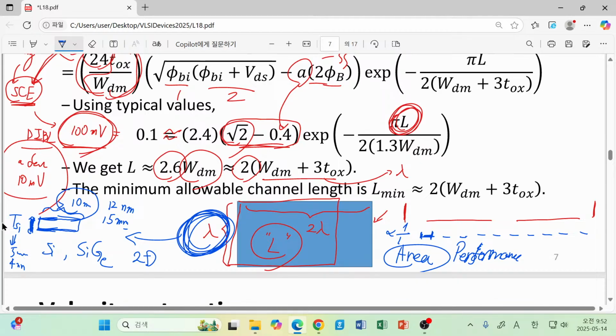We are quite at the extreme of our allowed scaling rule. We are already making full use of this scaling property. So the next thing is, well, 15 nanometer, 12 nanometer. It's good. By introducing this kind of length scale, the transistor, of course, has an intrinsic channel. Its length is about 15 or 16 nanometer, but it is not all of our transistor.